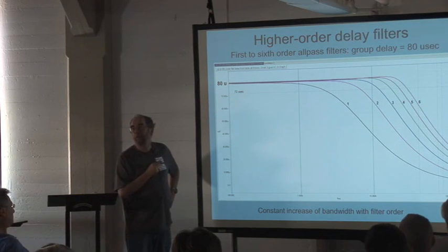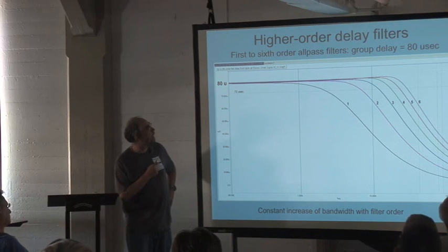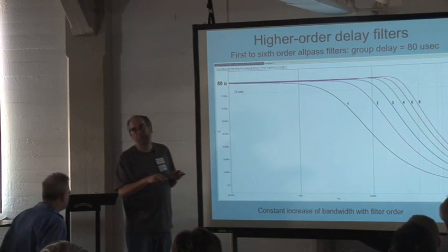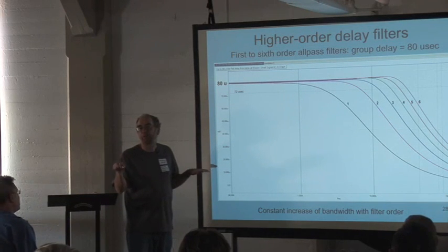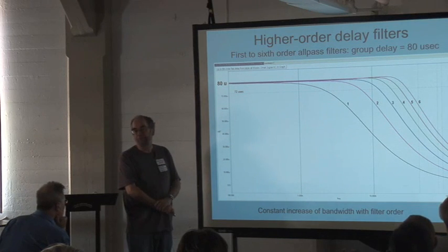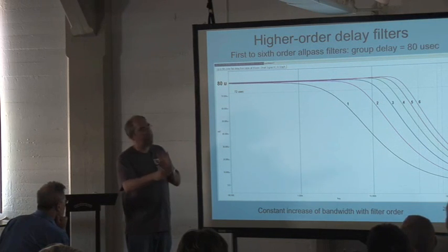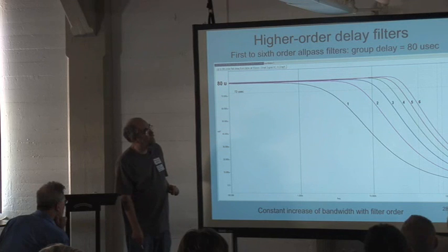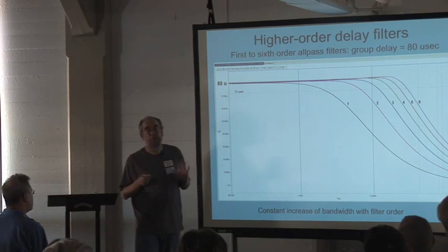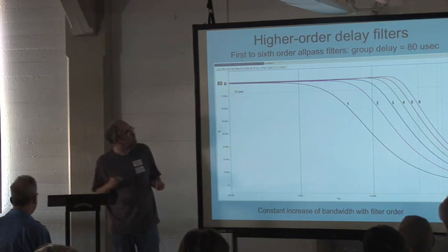Now, you probably think, well, how accurate does it have to be? That's a good question, because an inaccuracy in the group delay turns into an inaccuracy in the amplitude response. It will no longer sum exactly to flat. But as far as I can work out, so long as you're 10% down, well clear of your crossover frequency, at least an octave above it in this case, then it's probably going to be a negligible effect on the summed amplitude response compared with your tolerances in your drivers and so on.